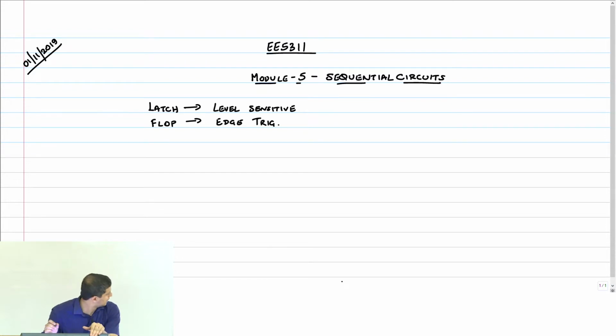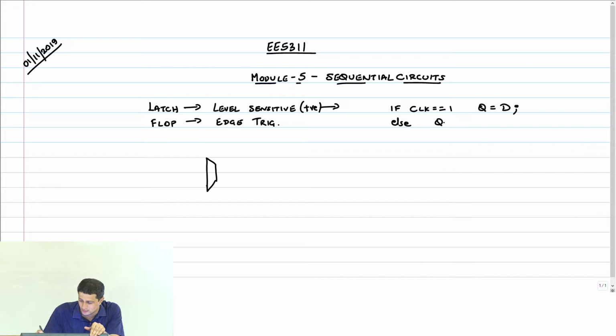Okay. So we also discussed one very simple implementation of a latch, which is using a multiplexer, right? If you look at the latch, by default it's a positive latch, sensitive to the positive cycle of the clock. So if clock equal to 1, then Q equal to D, else Qn plus 1 equals Qn, hold the state, right?